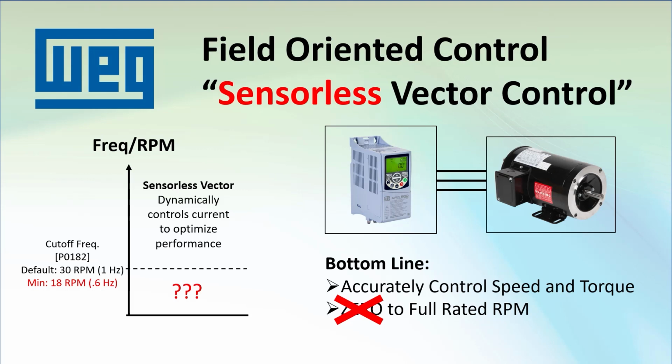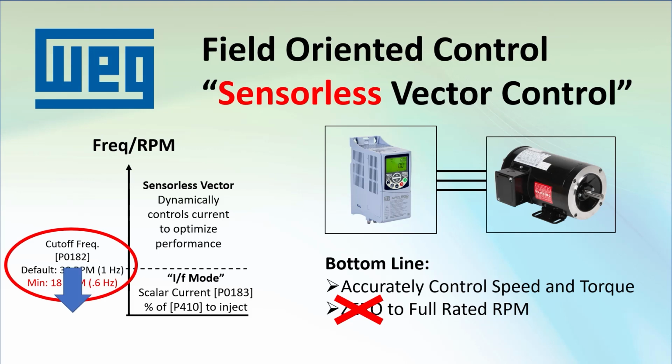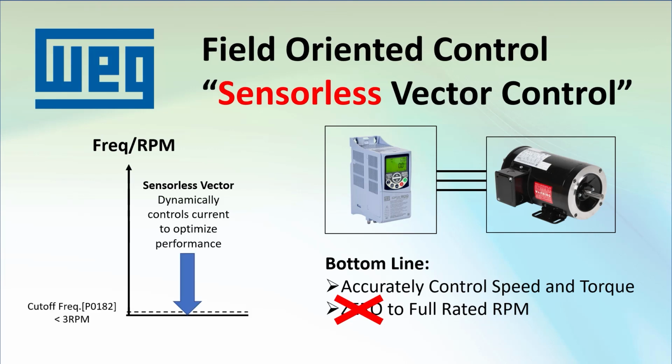What happens if you try to run the drive below that cutoff speed? Well, the drive automatically drops out of sensorless vector and goes into something called IF mode. That is, it simply pumps a fixed amount of current into the motor. It's kind of like volts Hertz, except it controls the current instead of the voltage. The scalar current value is set in parameter 183. Now this is the percentage of the motor's magnetization current in parameter 410, which is determined during tuning. It's not a percentage of the rated current. By the way, if parameter 182 is less than 3 RPM, the sensorless vector will always be on. It won't transition to the IF mode.